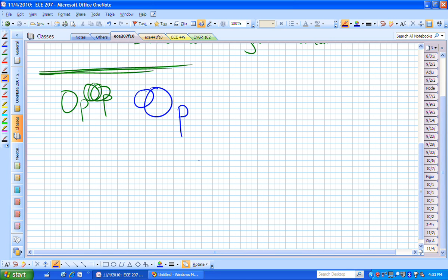Now that you have it energized, it has these particular features. That is, those currents I sub x and I sub y are 0. V sub d, if it's in a linear operating range, will be 0. And that results in negative gain amplification. That's all that particular expression says.